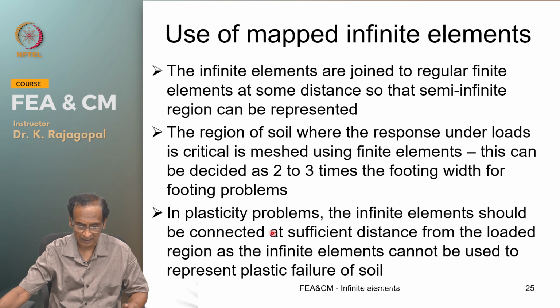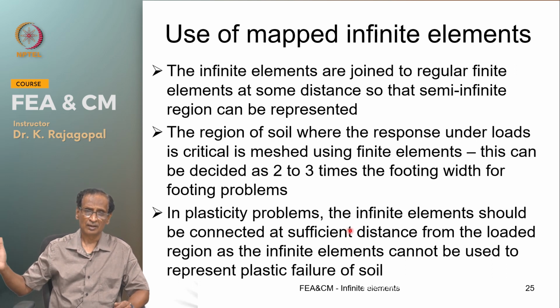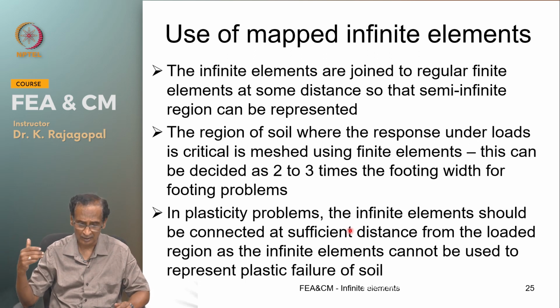And in the plasticity problems, infinite elements are connected at a sufficiently far off distance that we can directly assign linear elastic properties for the infinite elements, so that there is no failure.